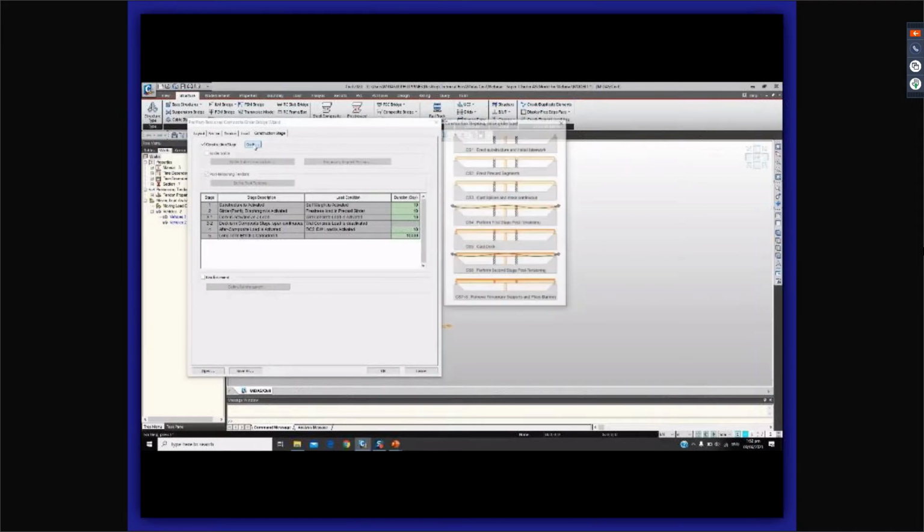The construction stage being shown here has up to 8 construction stages. So whichever is applicable for our model, it automatically generates. For example, CS1 is where it directs the substructure and installs falsework for any. So we have that substructure, and then the girder part. So our composite girder is divided into two parts, the girder and the slab part. So in CS2, girder parts are activated.